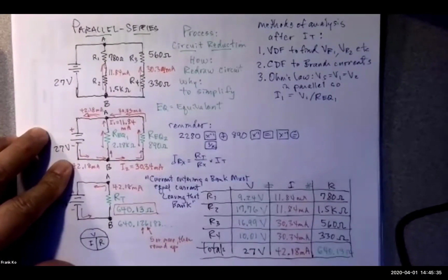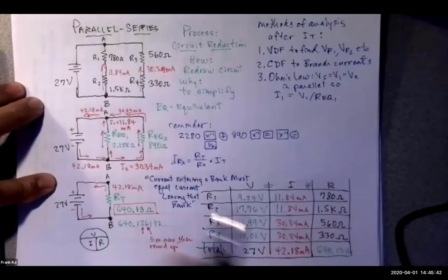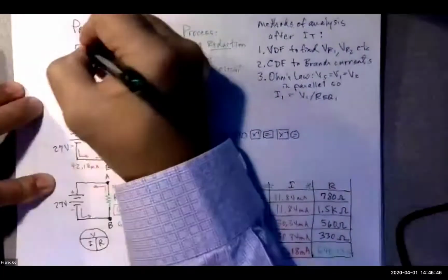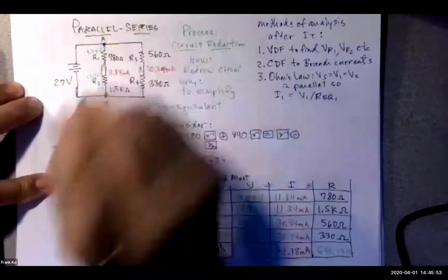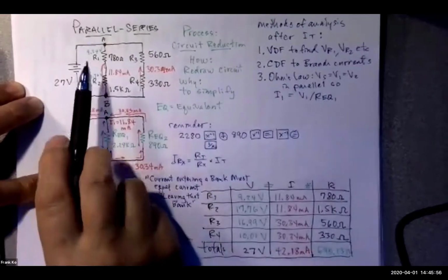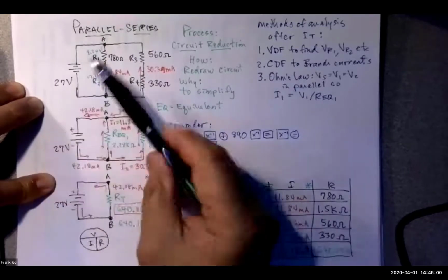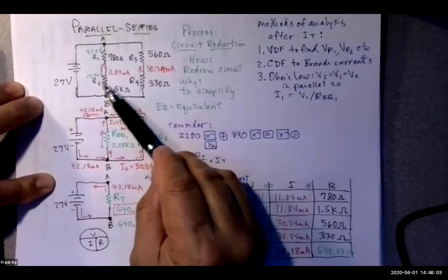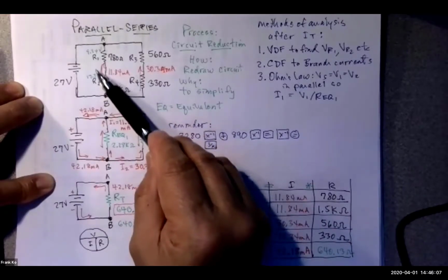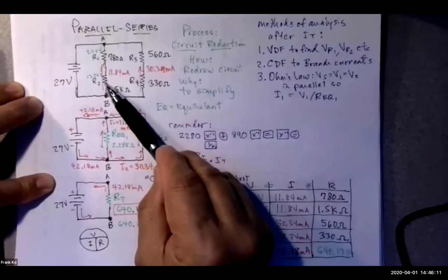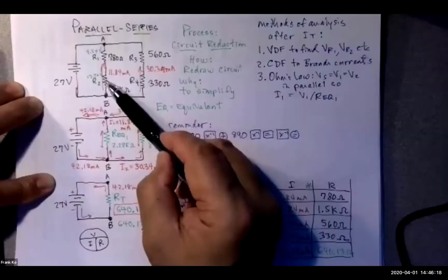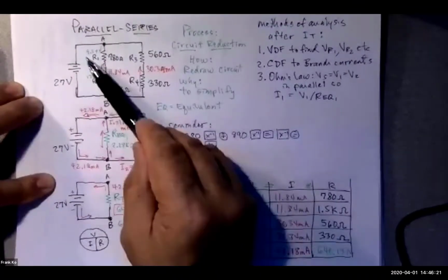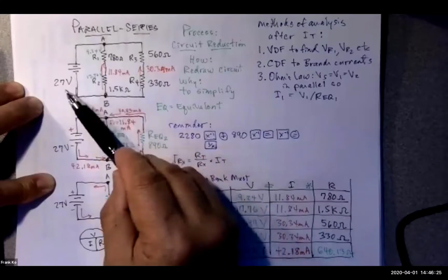I'm going to write this information in on our schematic. I have 9.24 volts here, and I have 17.76 volts here. Take a look at that first branch, my friends. I wrote 9.24 volts across this first resistor, 17.76 volts across the second. Should these two voltages add in this branch to give us the 27 volts over here? Yes, they do. Just like resistors in series add, their voltage drops in series also add. So the 9.24 plus the 17.76 add exactly to 27 volts.